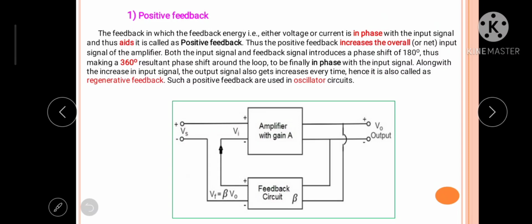Both the amplifier and the feedback network introduce a phase shift of 180 degrees, which makes a total of 360 degrees around the loop, which is finally in phase with the input signal. Along with the increase in input signal, the output signal also increases every time. Hence, it is also called regenerative feedback. Such positive feedback is used in oscillator circuits.